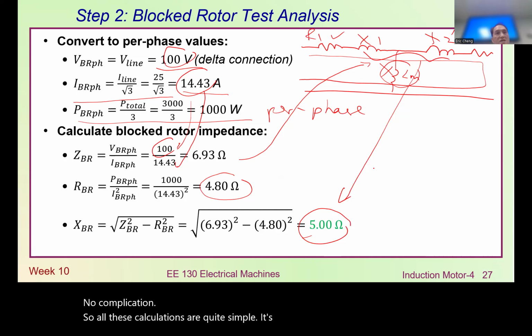In adjacent windings, if the insulation is weakened, then when you have a transient voltage, our voltage here will usually be a really nice 120. But due to some transient, some large machine turning on, the voltage suddenly jumps. That transient will break down the winding, break down the motor. So that's why we don't overload the temperature too much. 75 degrees is quite a limit.